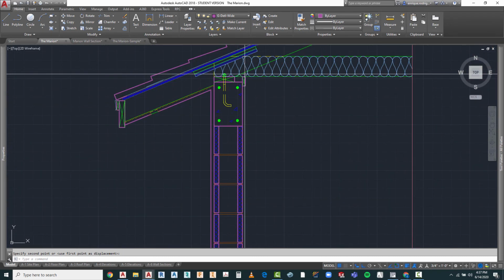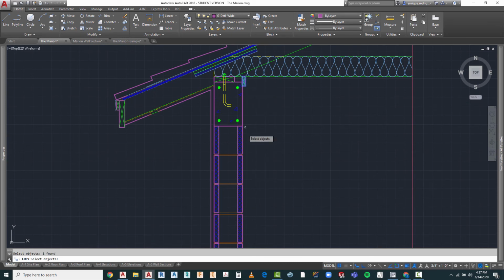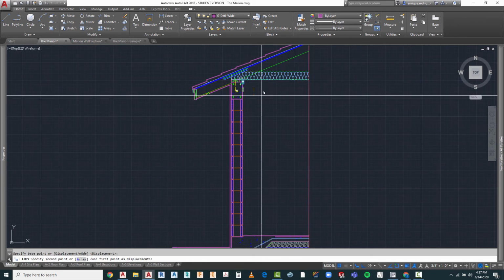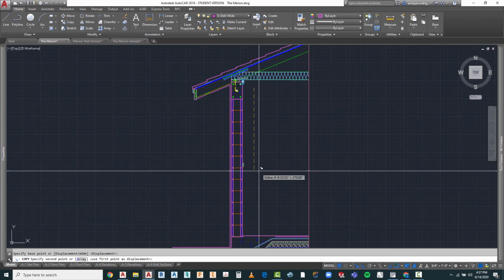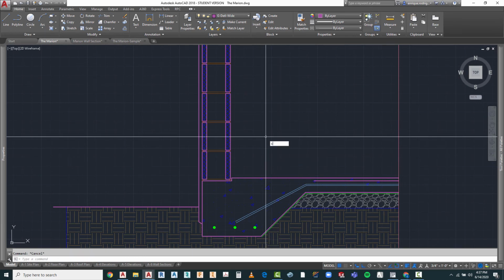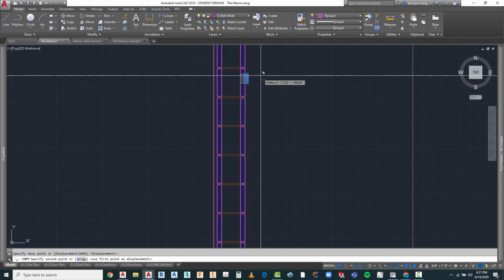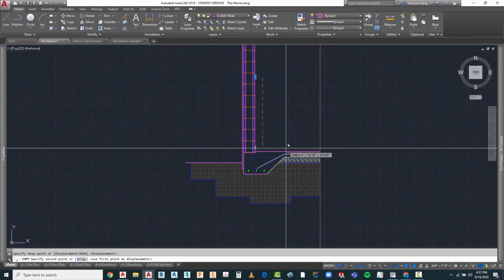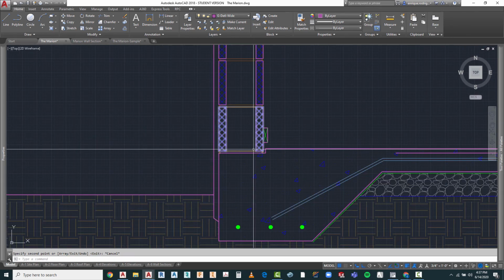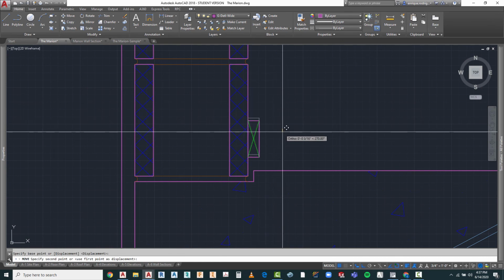And it also has a very, very important function. If our wall is higher than 8 feet, which it is, we need to have one of these roughly at midpoint. And then we're going to put one last one on the bottom, which is going to represent a nailer for our baseboard and the bottom of our drywall.